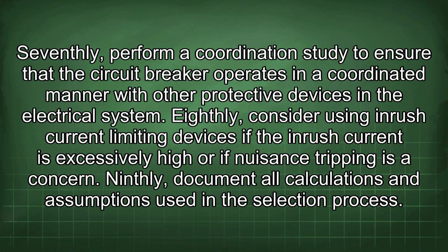Seventhly, perform a coordination study to ensure that the circuit breaker operates in a coordinated manner with other protective devices in the electrical system. Eighthly, consider using inrush current limiting devices if the inrush current is excessively high or if nuisance tripping is a concern.